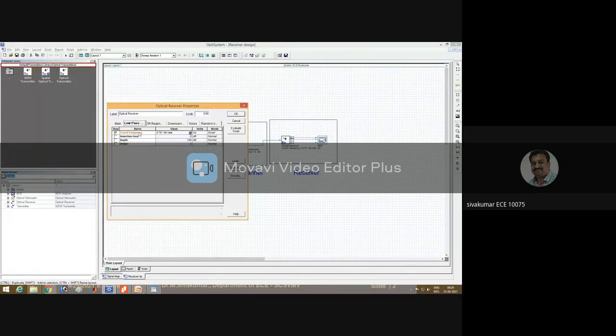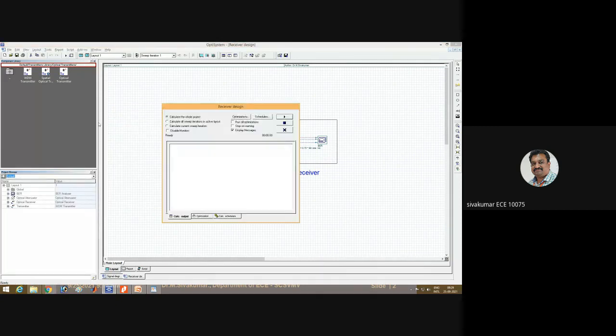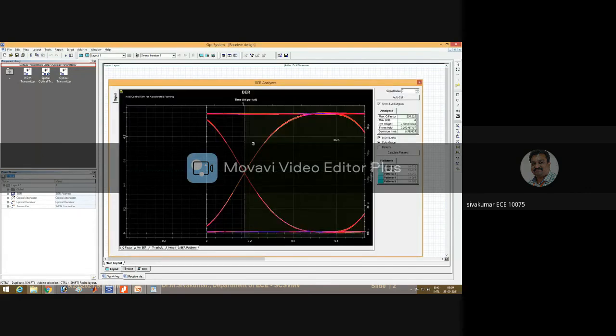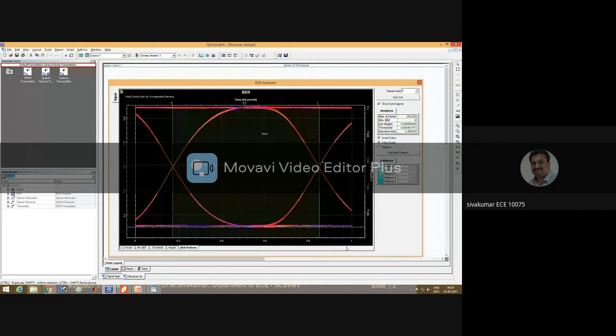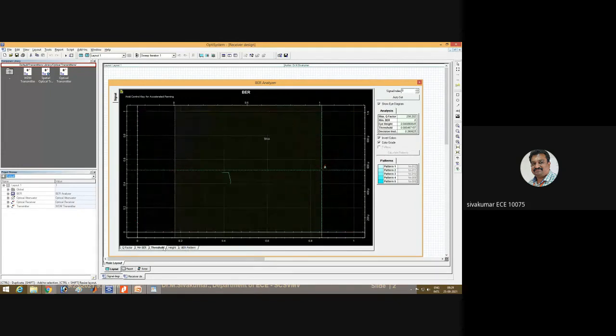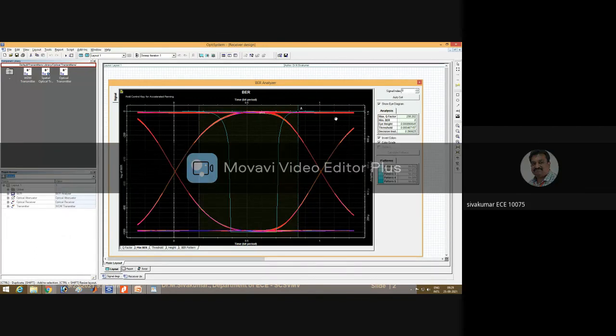Okay, then for the low pass filter cutoff frequency, you set 0.75 times the bit rate, and there is no change in any other tabs. Okay, just run the simulation, and just observe the diagram like this. Okay, we find the maximum Q factor value, BER pattern, threshold, and minimum BER value. In this manner, you observe the output and get the bit error rate analysis.